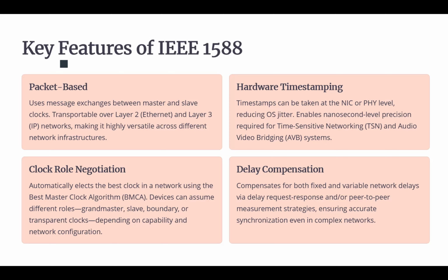So instead of relying on the computer's operating system, which might be in a high traffic, high processing situation, very busy and with a high level of delay, we can use the time synchronization at the hardware level. So it captures the exact time a message leaves or enters the device.